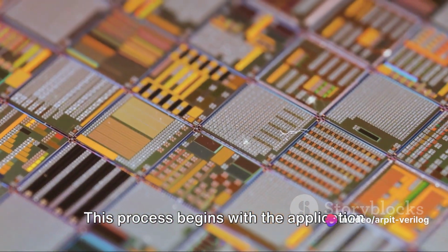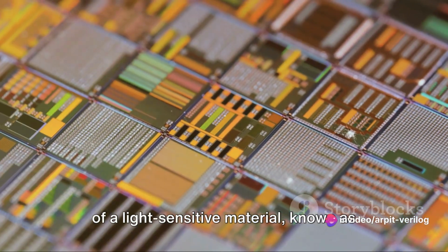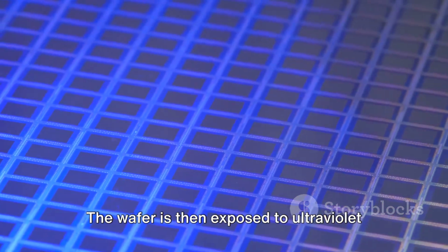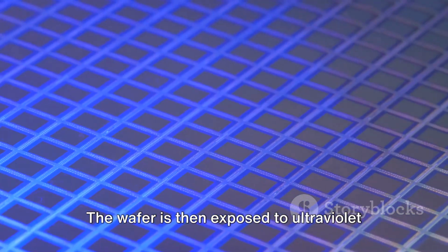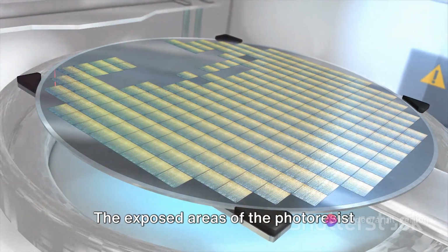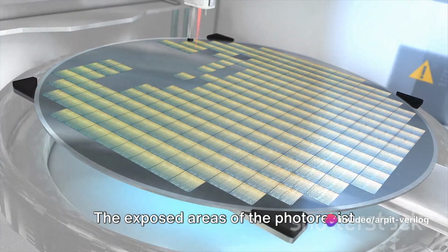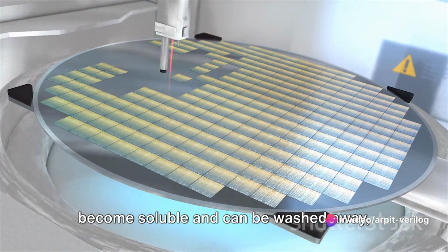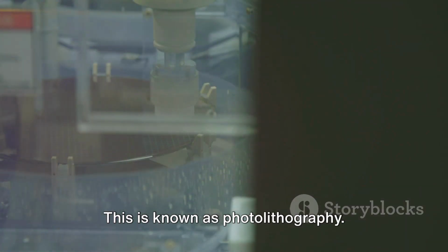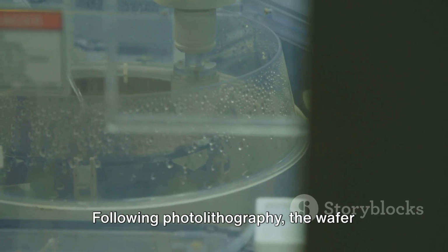This process begins with the application of a light-sensitive material known as photoresist to the silicon wafer. The wafer is then exposed to ultraviolet light through a mask that carries the design of the chip. The exposed areas of the photoresist become soluble and can be washed away, leaving behind the pattern of the microchip etched on the wafer. This is known as photolithography.